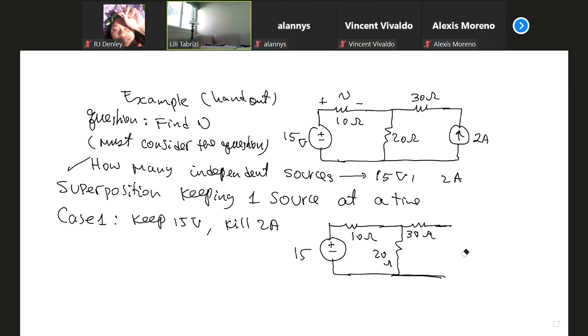Let's go to Beltran. Jesse Beltran. Yeah, I'm here. If I kill the current source, what should I do here? Do you add a resistor? There is no resistor. There is a current source, and I'm turning off the current source. The current is not generated. The current is zero. What shows zero current? What should I put? Okay, they give you this circuit. They ask you to redraw the circuit and kill 2 amp. Okay, this is redraw, kill 2 amp. What do you place here? What should I do here? The terminal that the current source is.